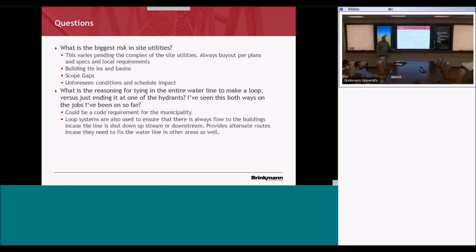What's a finger drain? It is a sock pipe, 10 feet long, wrapped around the base. You have to run it through your local municipality to make sure they're okay with it, but then you create drainage below the plane of the finished pavement. I was actually surprised: the areas where that was installed, nothing pumped through the rock we put down, they were all in good shape. At the south end of the parking lot, where there was no area inlet or finger drain, it all pumped through, and we're going to have to muck it out, which we knew was coming anyway. But it helps a lot, and they're cheap.